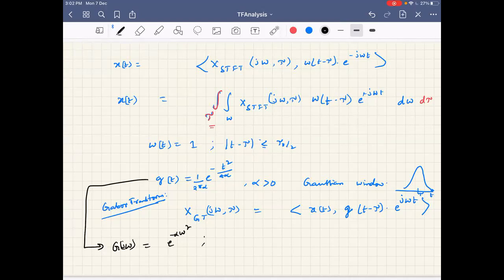This Gabor window function can alternatively be defined with an additional complex term. This complex term enables a sinusoidal signal being tapered off by a Gaussian. So the window function also has a sinusoid of a particular direction.